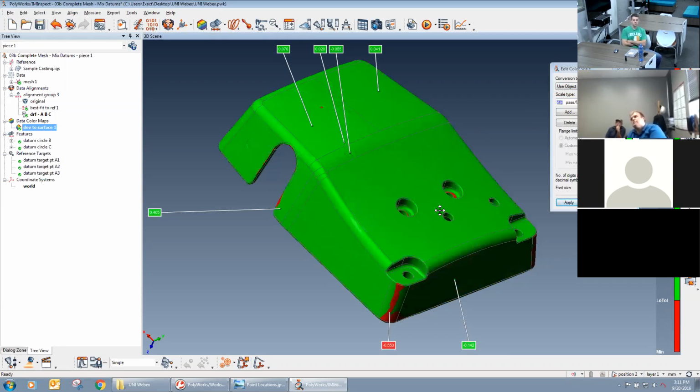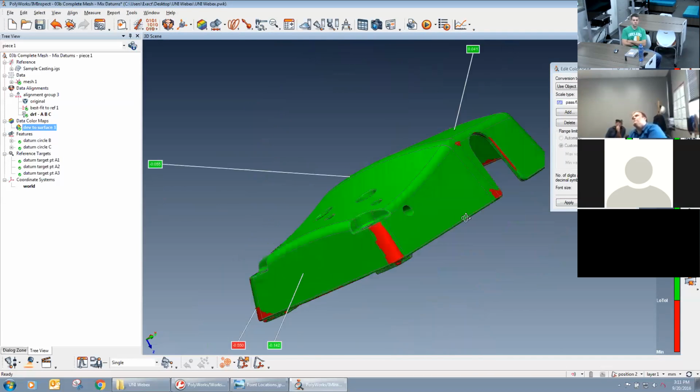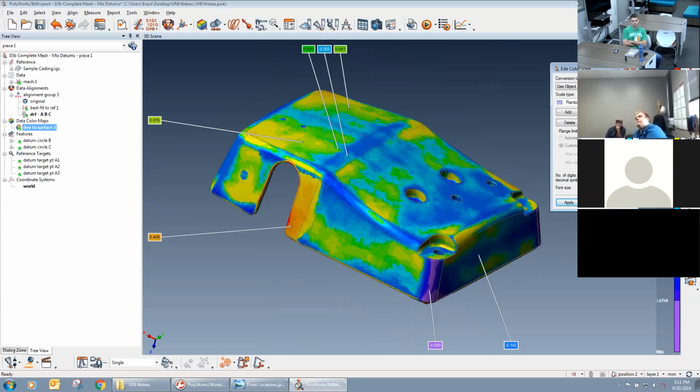So looking here, if 0.5 millimeter were our tolerance, it's showing us in red where the fail marks are. And then there's the rainbow that does have pass-fail with a different color for minus and max, and then rainbow in between. So with this color map, you don't get numbers as far as the colors. You get whether it's 0 or getting warmer, getting to tolerance, or out between upper tolerance and maximum.